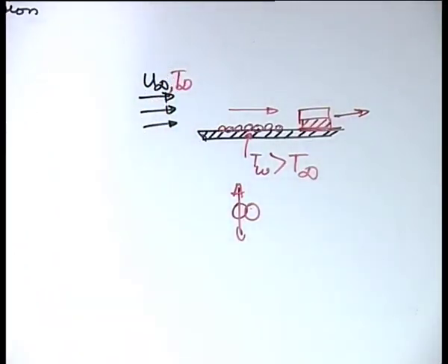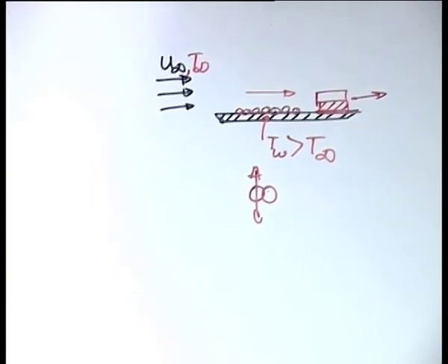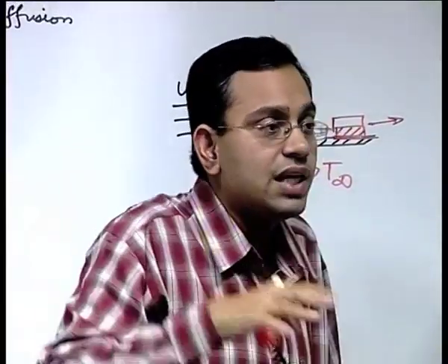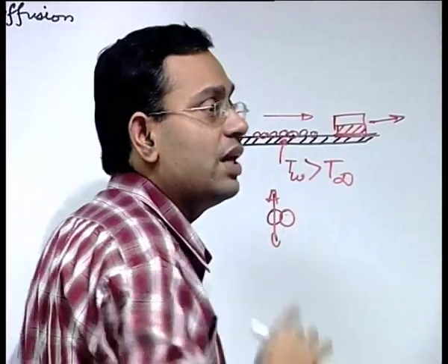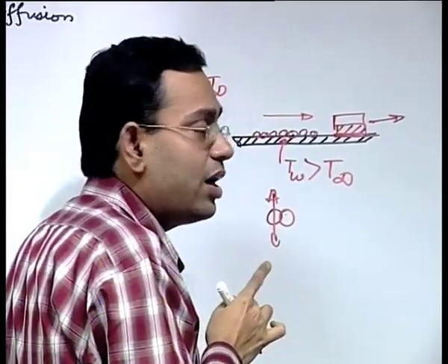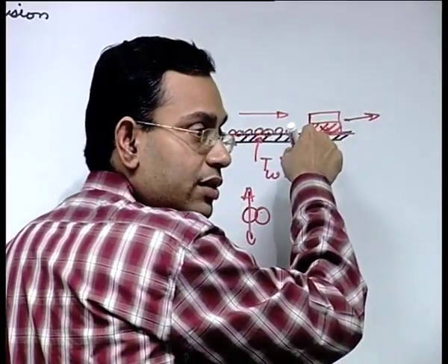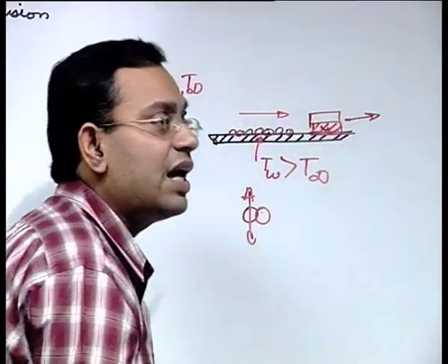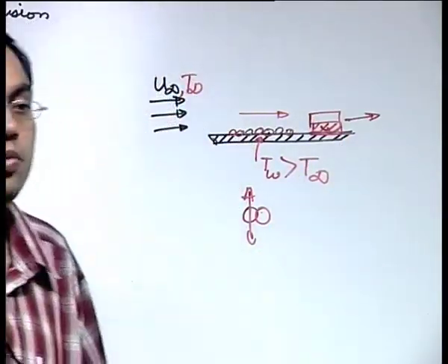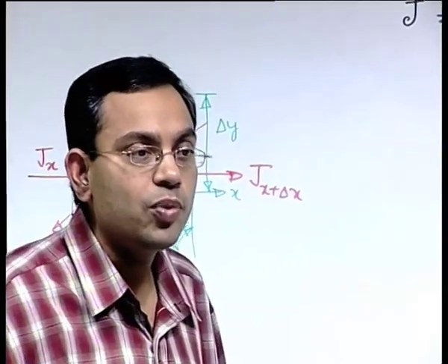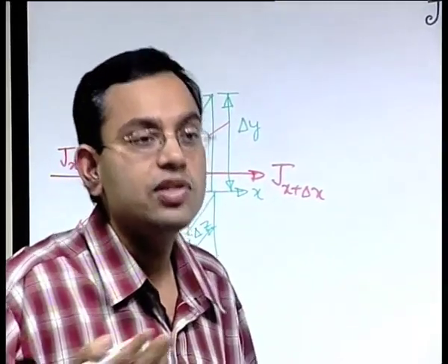It is not directly in contact with the wall. If it is not directly in contact with the wall, then it would have been transported with a free stream velocity, but it does not do that, because it also feels the effect of the wall. How does it feel the effect of the wall? Not directly in contact with the wall, but implicitly through the effect of this intermediate fluid element. This intermediate fluid element is like a carrier which carries the message that there is a wall from the wall towards the outer fluid, and the fluid must possess a property by which this message of momentum disturbance is propagated inside the fluid. That property is the viscosity of the fluid.